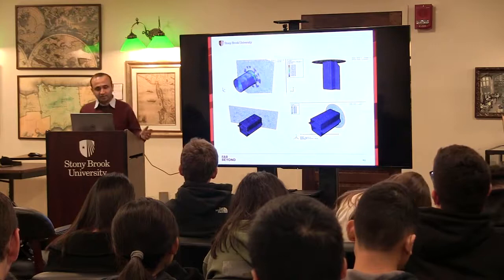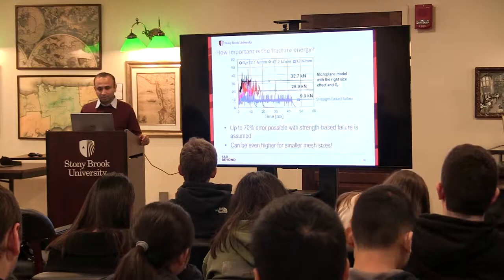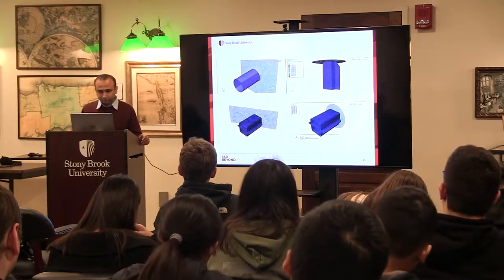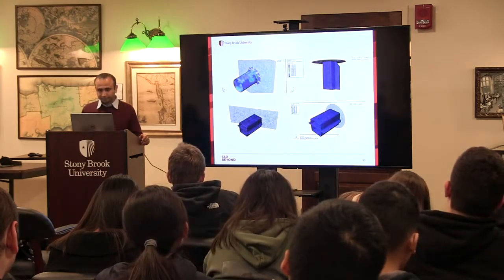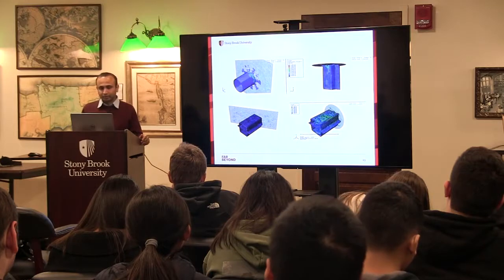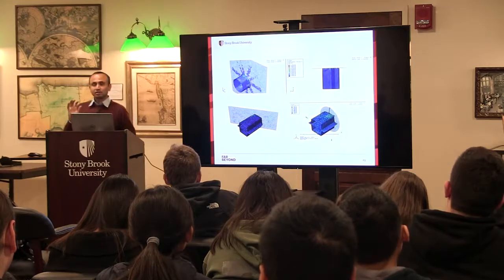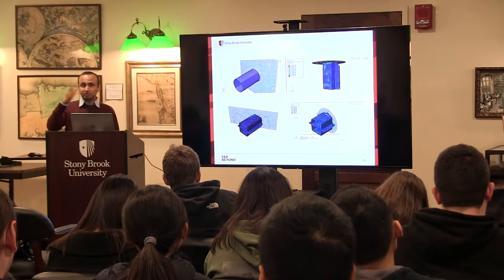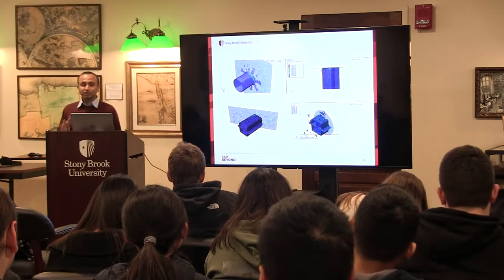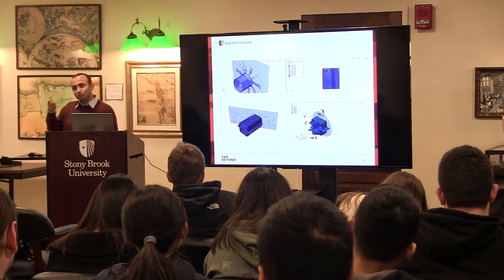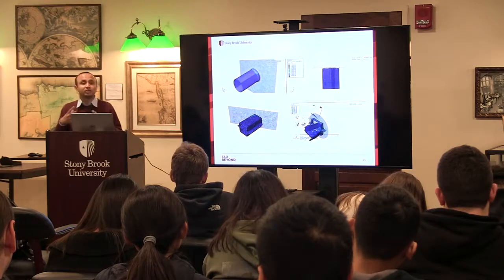These were some different designs they wanted to test out, and then you can model them. Again, the essential ingredient of this is the fracture energy. If the model is based on the correct fracture energy, measured through this size method, it can match this kind of behavior very well. And then you can use it to design. You know how thick to make it, how large to make it, and how much energy it will actually contribute.